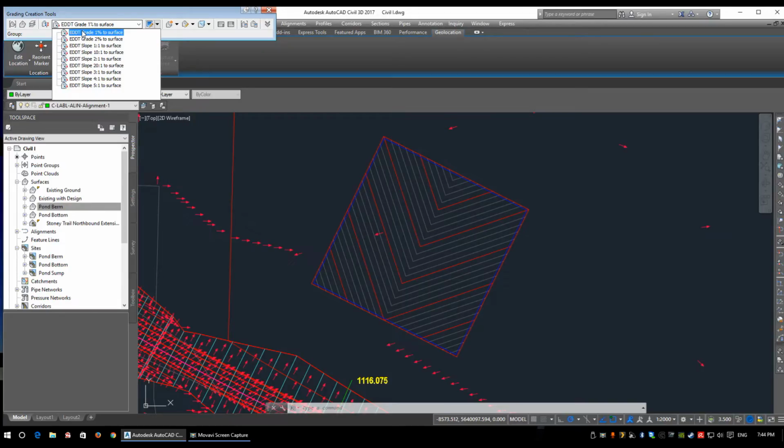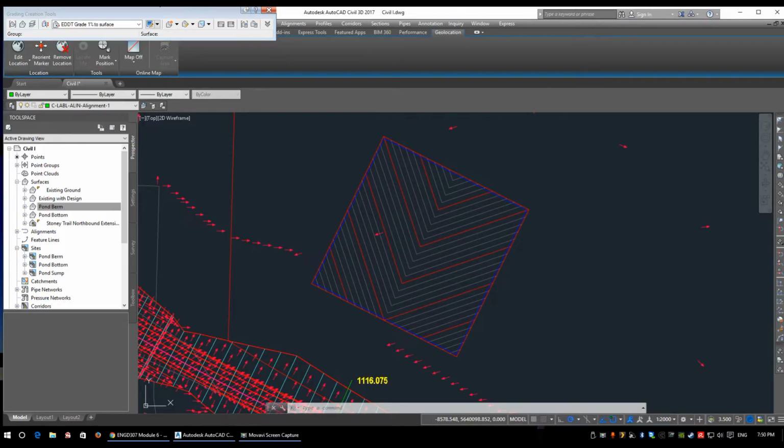Now, conforming to the City of Calgary design guidelines for their ponds, let's quickly go look that up. So in our design specs, it says a maximum interior side slopes in active storage zone are 5-to-1 to 7-to-1. So we're just going to treat the entire pond as 5-to-1. So we actually do have a 5-to-1 in here, so we want to slope 5-to-1 to surface.